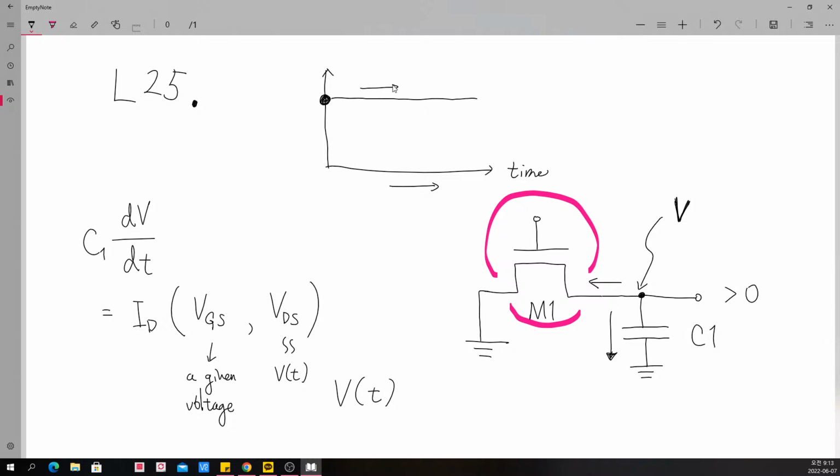But that is just an ideal case, and unfortunately in our transistor we can find many non-ideal effects. Even though we have applied a very low gate voltage, we can still have leakage current. Then maybe we will find that there will be certain degradation of our voltage level, and if this level goes below a certain level, for determining whether this value is high enough or sufficiently low, then that is related to the change of the bit.